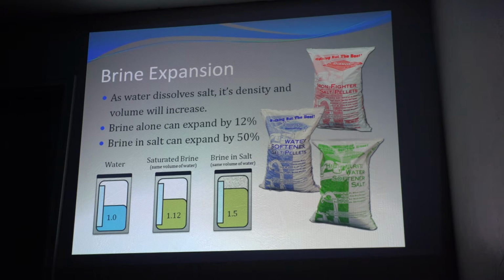So how do you correct the issue other than changing salt, do you change the amount of water? Nope. If you change the amount of water, you're going to dissolve a different amount of salt. That's what a lot of people want to do, they say, oh, we turned the brine down. Well, you're not going to get soft water anymore either. That's right. You've got to remember, it's a fixed amount. A gallon of water will dissolve 3 pounds of salt. It's not selective as to whether it's rock salt, solar salt, or granulated salt. It doesn't matter. A gallon of water will dissolve 3 pounds of salt.